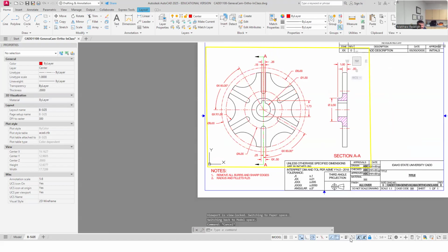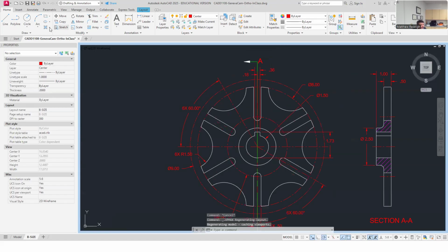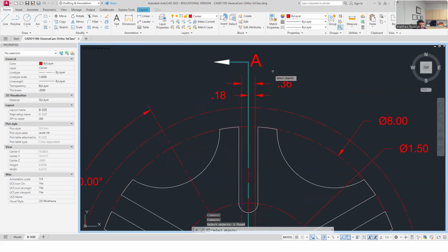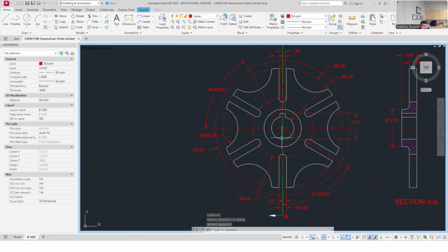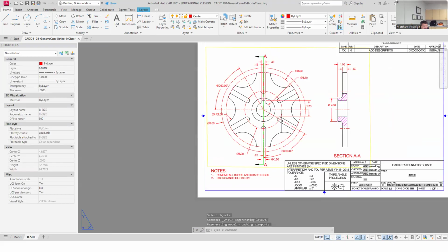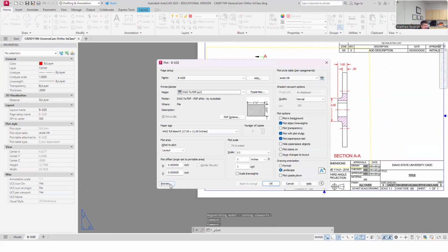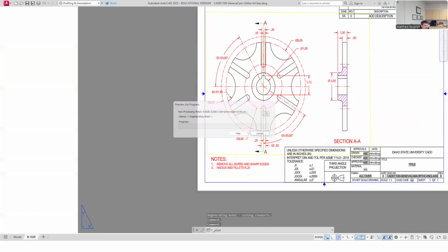I'm going to go back into this and just do a quick line precedence here, which is front to back or back to front. I'm going to bring my cutting plane line to front, I think. And I might change its line type scale. I might actually look at it on a PDF and see what it looks like. We haven't used that line before yet, so I'll Control P this thing. It should have the plot style already set up. And that's what it looks like.